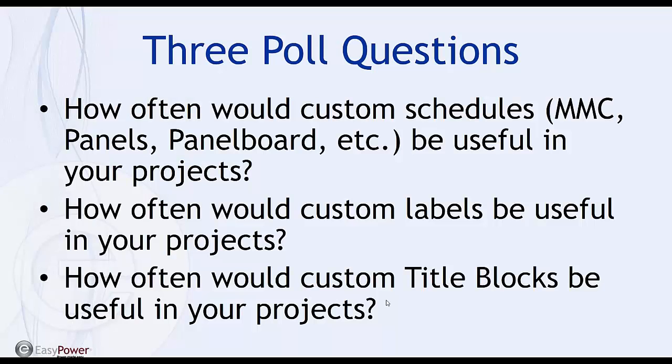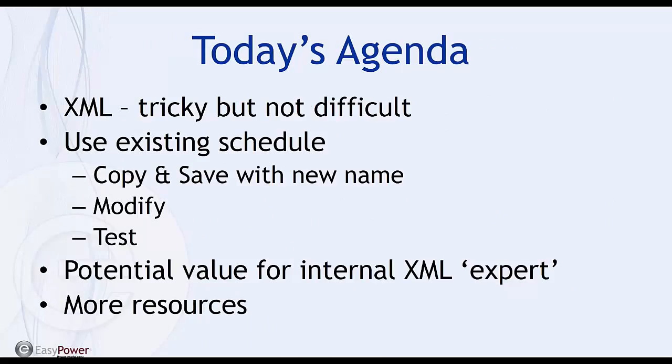So with all that in mind, let's jump into today's agenda. All of these subjects that we're referring to utilize a language called XML, and it's tricky, but it's not difficult. And what I will show in this example is, because all these schedules and blocks and labels exist in a template form already, if you want to customize something, just make a copy of the one that's there, make some modifications, test it, and then you'll be able to utilize the new version wherever you want to.